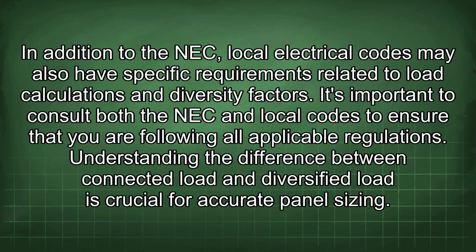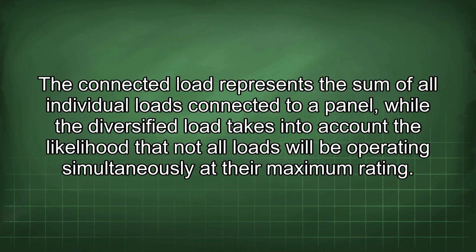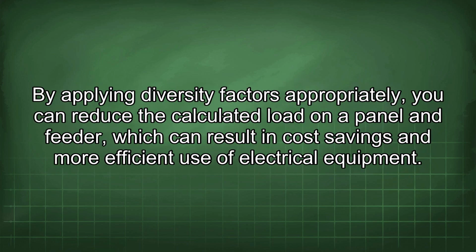Understanding the difference between connected load and diversified load is crucial for accurate panel sizing. The connected load represents the sum of all individual loads connected to a panel, while the diversified load takes into account the likelihood that not all loads will be operating simultaneously at their maximum rating. By applying diversity factors appropriately, you can reduce the calculated load on a panel and feeder, which can result in cost savings and more efficient use of electrical equipment.